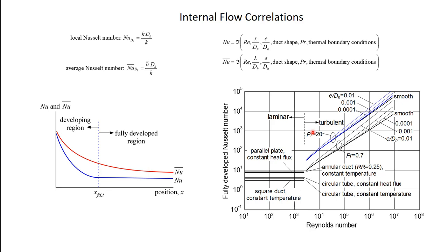So if we come down here and look at these Nusselt number solutions, one thing you'll see again, right at 2800, you've got a very dramatic shift in behavior, right? And actually, if you want to think about it, everything that matters for a laminar flow doesn't matter for a turbulent flow. Everything that matters for a turbulent flow doesn't matter for a laminar flow. So these two different flow regimes could not behave more differently from one another.